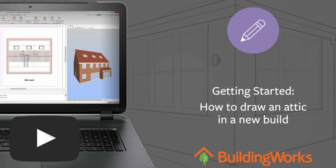In this video, we demonstrate how to draw an attic as part of a new build project. If you have the estimate module of BuildingWorks, you'll also be pricing up the attic as you draw it. To draw and estimate an attic, you create a new attic level on your drawing by copying the first floor level. Next, you select an attic roof type from the Roof drop-down menu.